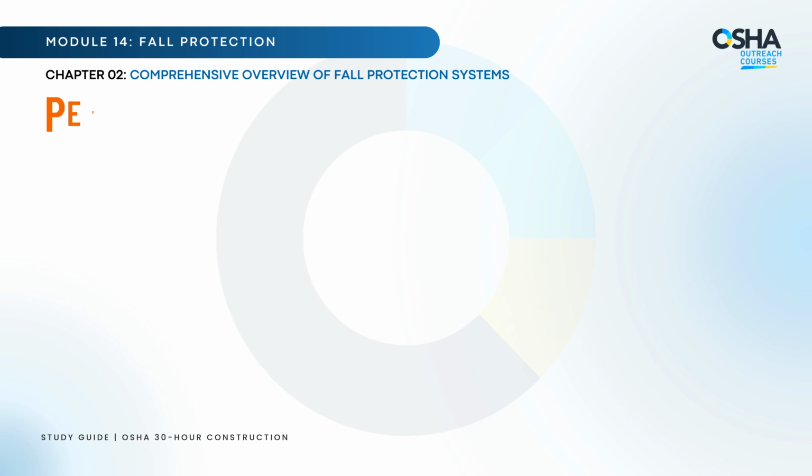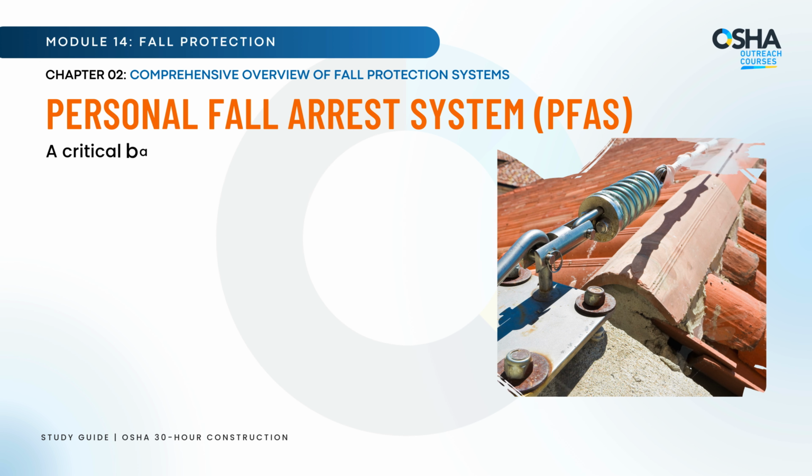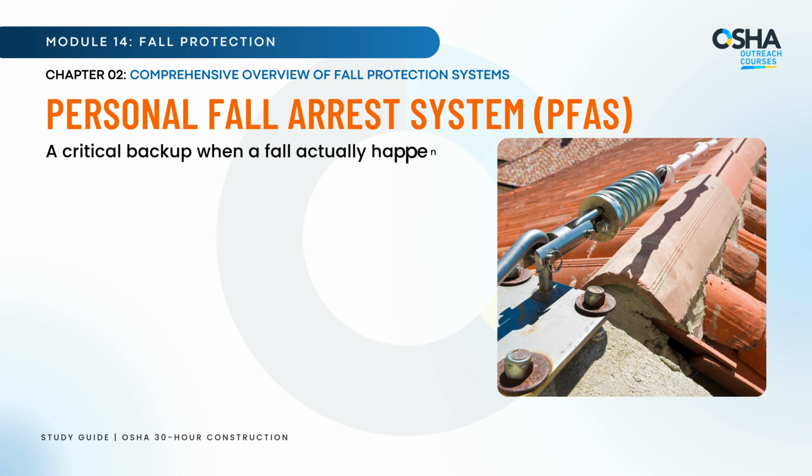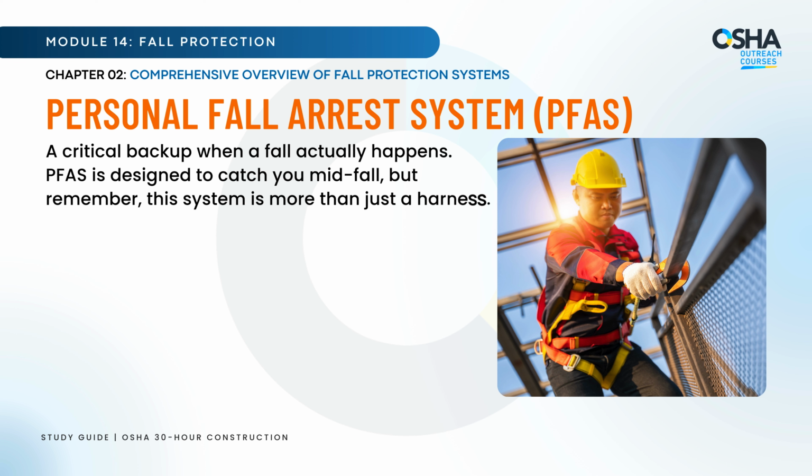Next up, Personal Fall Arrest System, or PFAS. A critical backup when a fall actually happens. PFAS is designed to catch you mid-fall, but remember, this system is more than just a harness. The key to an effective PFAS is fit.